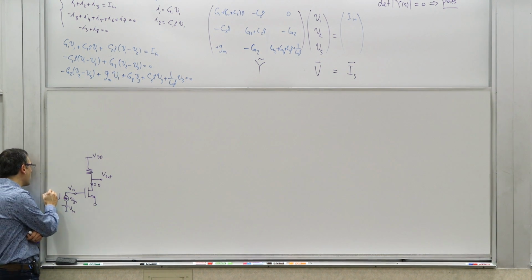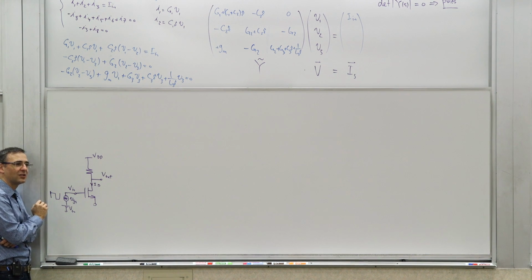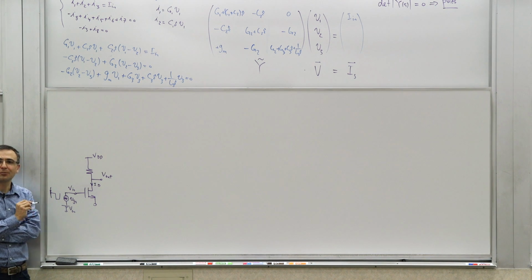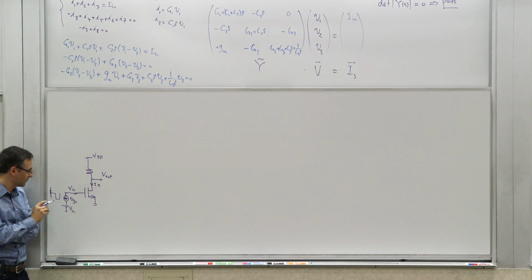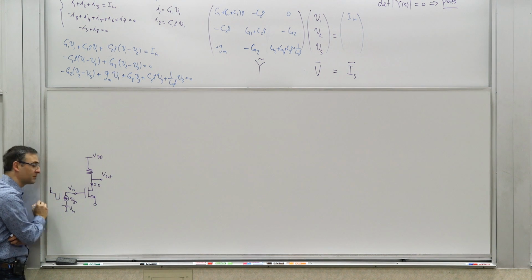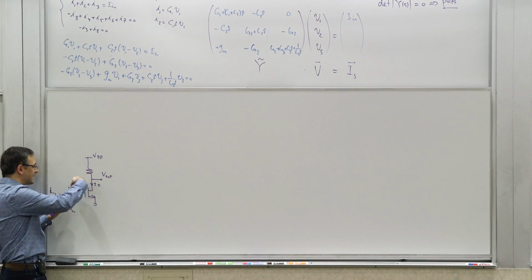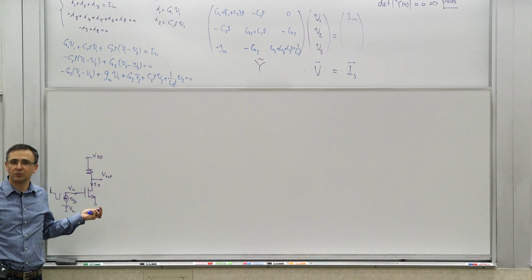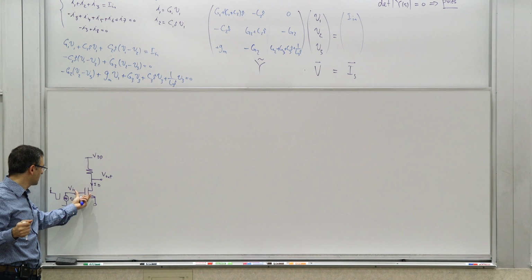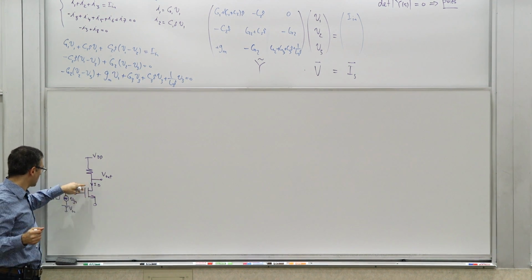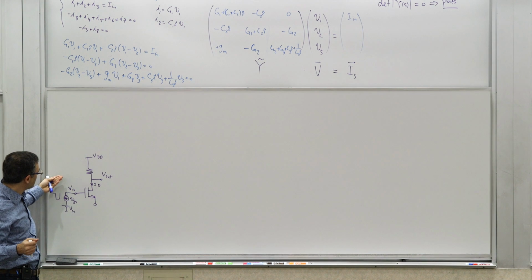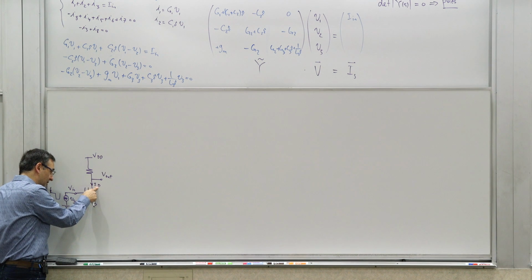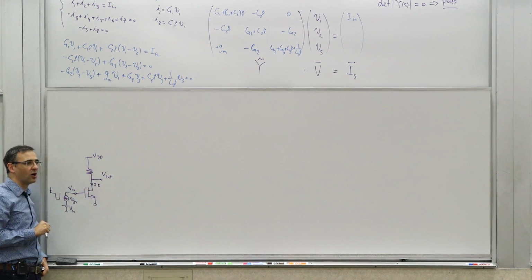So let's say you start with a point, the beginning of this thing, this is the voltage. You can say, okay, I am thinking about this as a DC operation point that I've been at. Let's say I start my simulation at this time. This circuit would be at some operation point. You can find what the currents and voltages would be, right? You can solve those equations. This is a simple set of equations, just to solve locally and statically. So you basically solve it and find what the DC current, or the total current, and the voltages are.